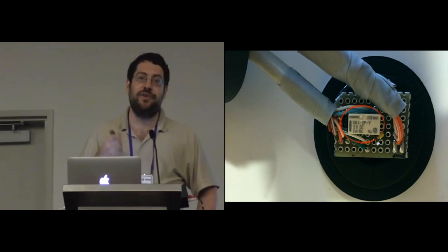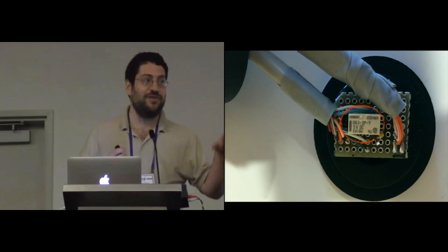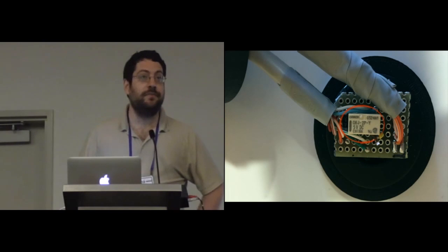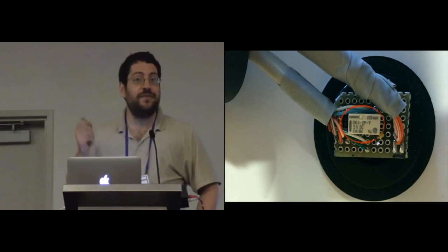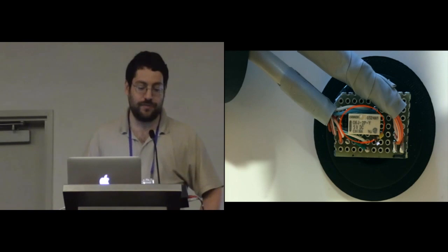What that means is when we built prototype measurement heads with a whole variety of solid-state switches, we'd find that they would still create a touch event even when the switch was turned off, which of course is useless for what we're trying to do. So a mechanical relay, because it's physically separate contacts inside of it, doesn't have that same sort of leakage issues.